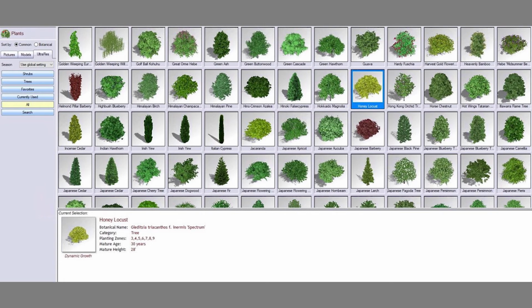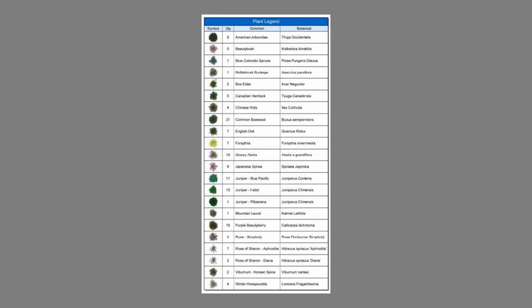When exporting a final design, you'll want to have a plant label that can identify and locate different plants within the design. AutoCAD, Dynascapes, and Realtime Landscape Architecture have unique systems for this. AutoCAD is a non-industry specific software, meaning that you will have to manually label and manually enter plants into a self-made plant list.